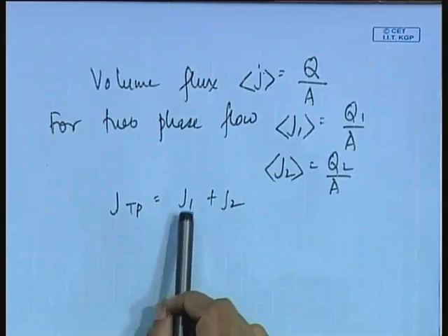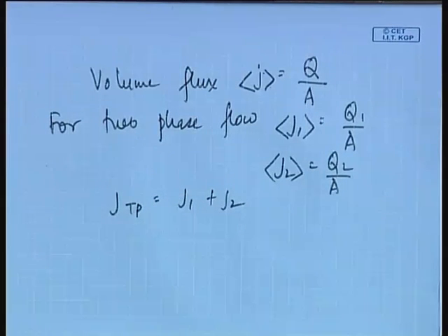Volumetric flux is a vector quantity, but here it is used exclusively to represent the scalar component in the direction of motion along the pipe. Under such conditions, it is numerically equal to the superficial velocity of the individual phase, but the basic definitions are different.